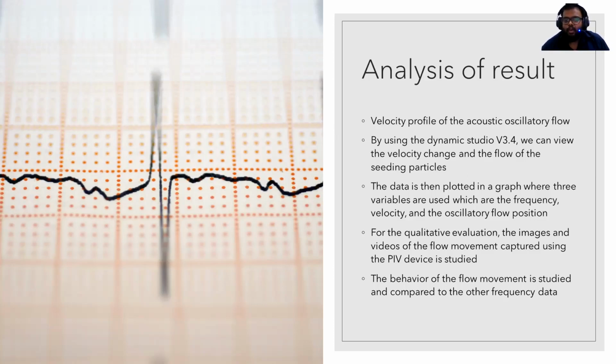For the qualitative evaluation, the images and videos of the flow movement captured using the PIV device are studied. The behavior of the flow is studied and compared to other frequency data that we have got from past studies. From this, we can determine which is the optimum stack length that can be used for a thermoacoustic device.